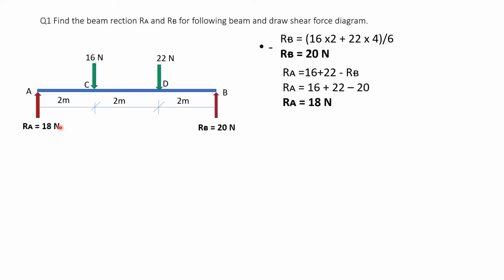Now let us come to the basics of shear force. How do we draw the shear force diagram? What is a shear force? Shear force is that we take a section and we consider the left hand side or right hand side of the beam and do the summation of all the vertical forces, and that summation is called shear force. Now let us see how we do it.